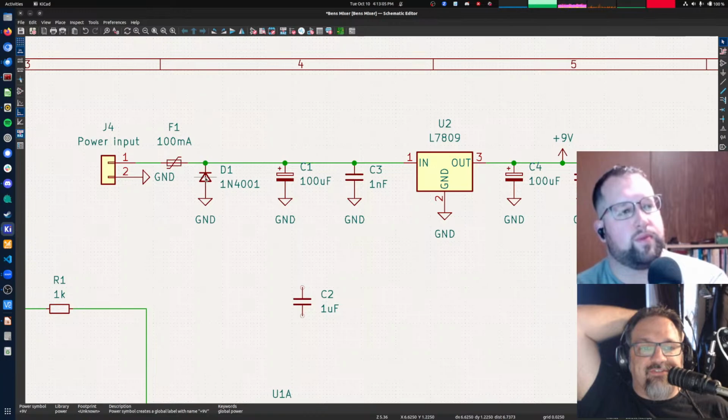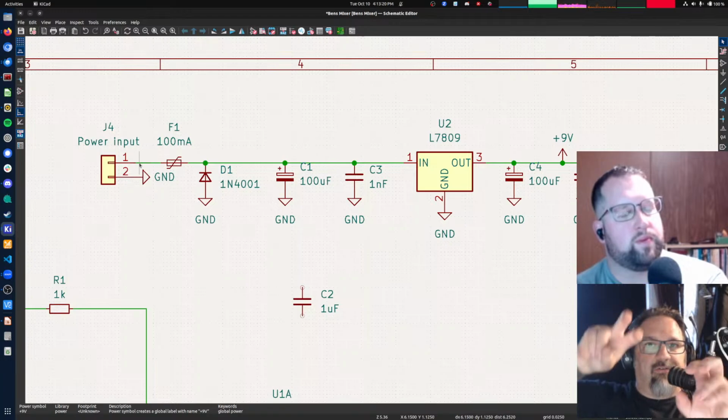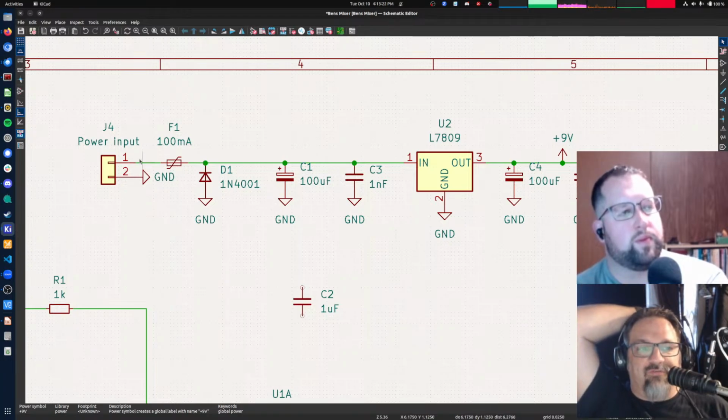And then I have a reverse voltage protection diode. So what happens here is this is the positive input and that's ground. If you accidentally flip those two, then you're going to end up with a negative voltage on here relative to ground, right? Because this will be ground and this will be positive 12 volts. That's the same thing as putting negative 12 volts here and ground.